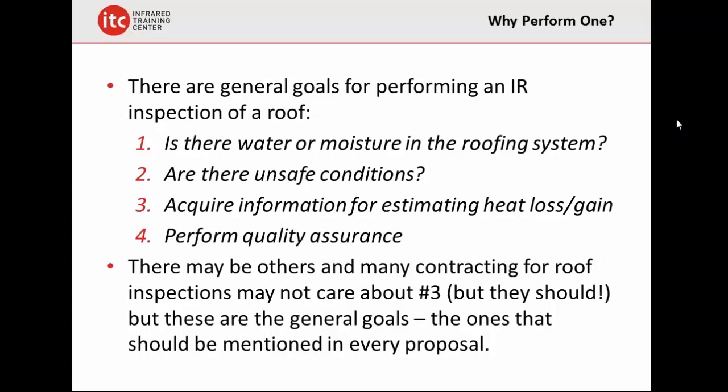Okay. So what are our goals for performing a roof scan? Well, we want to find out if there's water or moisture in the roof. And the big difference between water and moisture, in my definition, is that water sits on top of the insulation, moisture is in the insulation. So that's kind of like my definition.